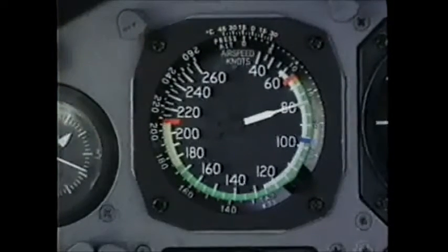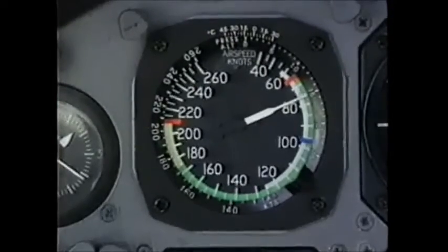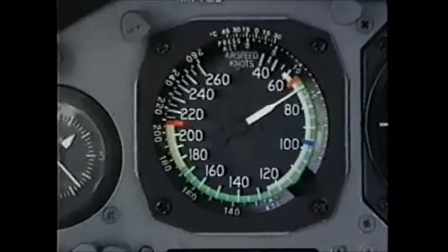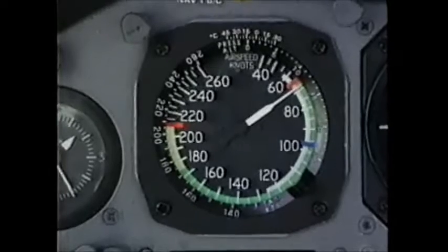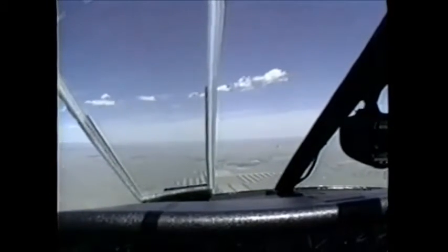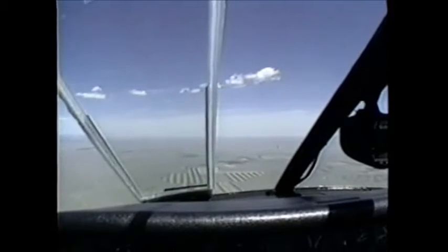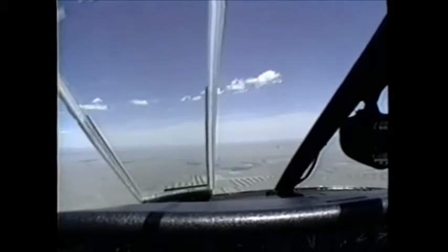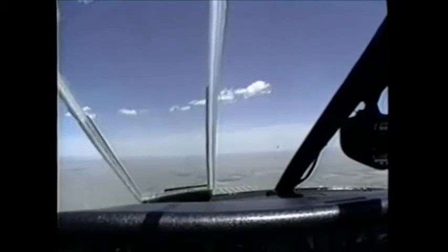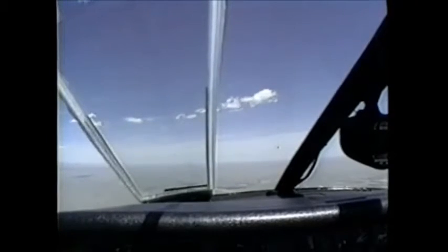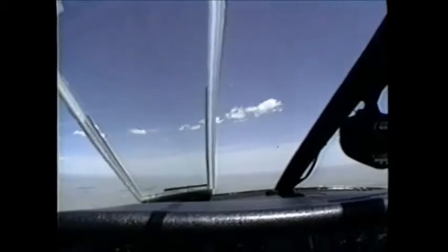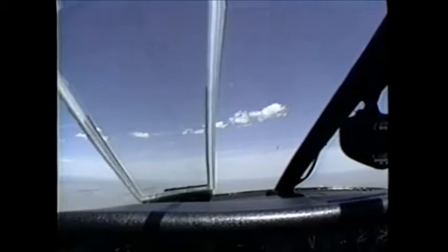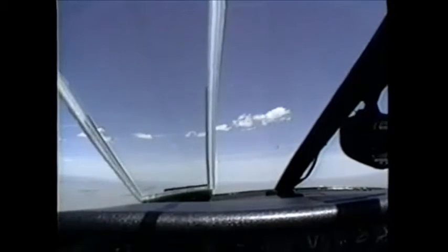As the airspeed decreases, you will eventually reach a point where full rudder is not effective enough to maintain the heading. As soon as this happens, recover by simultaneously reducing power on the operating engine and decreasing the angle of attack. As you regain directional control, complete the recovery by slowly increasing power on the operating engine and establishing the airspeed at VYSE.